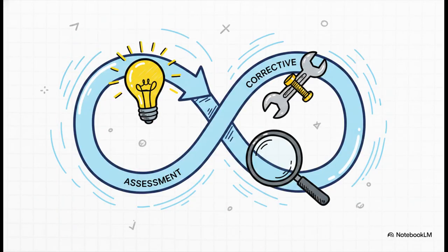Now, here is kind of the most interesting part of the whole framework. Phase 5, feedback, assessment, and corrective action. Unlike the previous steps, Phase 5 isn't sequential. It is literally the only phase that runs continuously from the very start to the absolute finish of the program. It tracks lessons learned, assesses effectiveness at every single stage, and deploys countermeasures immediately if a concern ever pops up. It's basically the engine of continuous improvement that keeps the whole APQP process alive and adaptive.